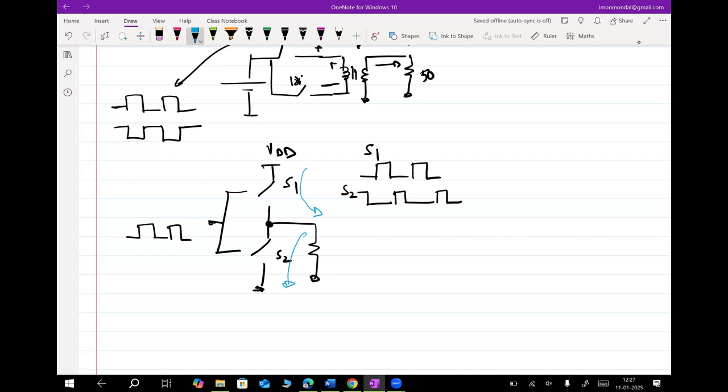And if you use some sort of smart filtering, you can basically see that all the current that you are extracting from the supply, here you need obviously a capacitive coupling and so on, all the current that you are taking from the supply is being used to drive the load. Nothing is used for biasing, because it's a switch. It's the inverter, right?